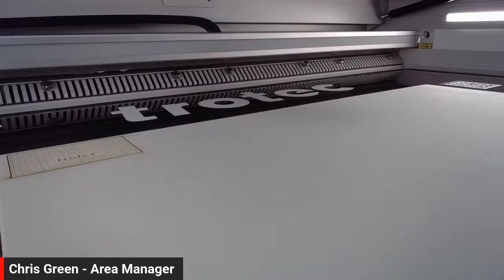I always have an overrun set on the machines in the showroom. What I mean by that is I have it preset so that before any job starts, it starts the extraction unit 5 seconds before the job starts, and it overruns by 30 seconds.